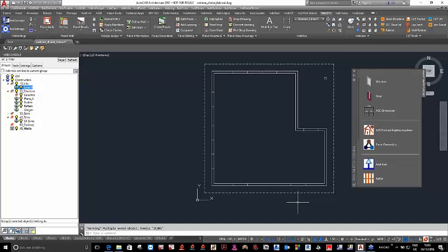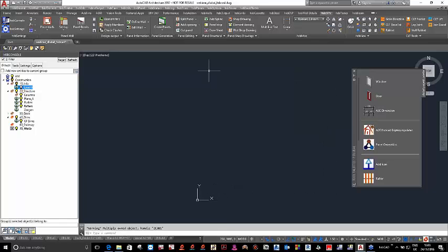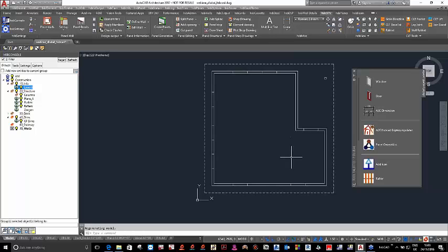Okay, now let me go back into our presentation. As I mentioned before, this runs inside of AutoCAD, in this case AutoCAD Architecture. What you see here on the left side of my screen is what we call the console, and you can nest different elements inside the console and turn them on and off as per your convenience. In order to simplify this presentation, I have created a footprint of what my building is going to be like. Basically, I'm going to create walls following the perimeters, and on top of that, I'm going to add my roof structure, which is going to consist of loose timber elements.